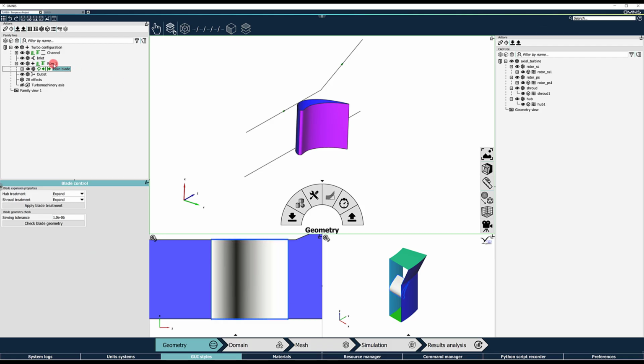Click on Row 1 and finish defining the row parameters which will be carried to the mesh context, such as row type, extra turbine, Francis turbine, inducer, extra compressor, extra fan, row periodicity, which defines the number of blades in the row and updates the 3D turbo view, the row rotation status, rotor or stator, an option to enable the tandem row feature, and gap fillet options. In this case, we have an extra turbine with 41 rotor blades with a tip gap of 0.4 mm at the leading and trailing edge.